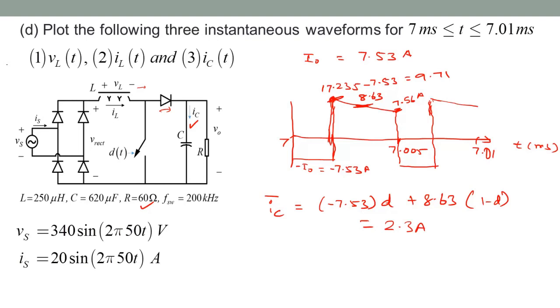Okay. So once again you can see that IC bar is not 0 as you would expect in DC-DC converters, but here this is AC steady state, where IC bar is not necessarily 0. It would be on a larger time scale. It would be fundamental frequency or twice the fundamental frequency current will have a non-zero, fairly low magnitude. Okay, so I think that completes problem 3.